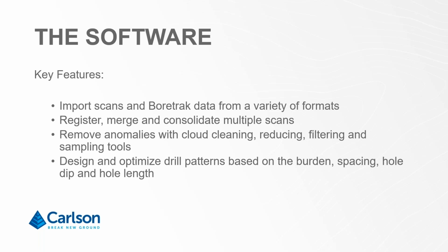You have the ability to register, merge, and consolidate multiple scans. You can remove any anomalies with cloud cleaning, cloud reducing, filtering and sampling tools. And then you can design and optimize drill patterns based on your burdens, your spacing, your hole depth, and your hole length.